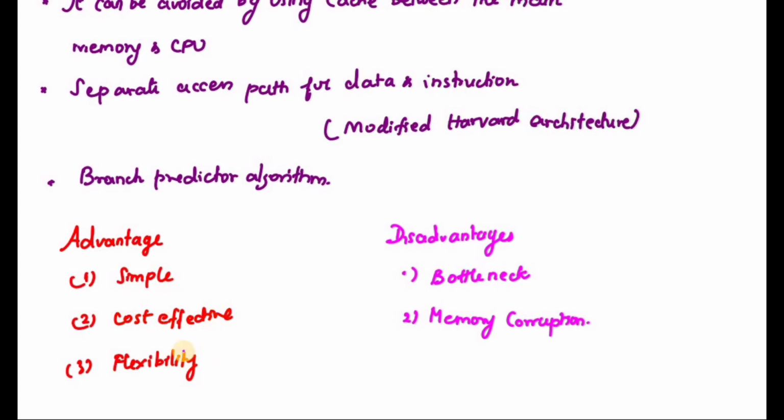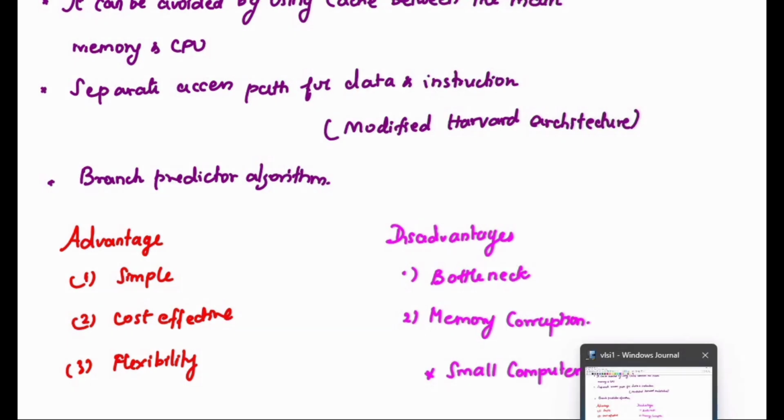It will be costlier, and most modern computer architecture is based on Harvard architecture. Since you are using a separate bus for both instruction and data, parallel processing can also be achieved with the help of Harvard architecture.